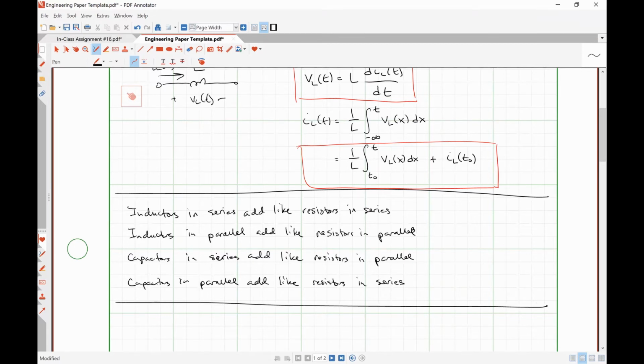Is that mostly because there's 2 equations and people probably get those 2 mixed up? No, it's more so because they don't look at the circuit during the transient condition, and that's very, very important. What I mean is that if you're not looking at the circuit at t greater than or equal to 0 plus, so if you look at the circuit at t equal to 0 minus and use that to compute your equivalent resistance, you're inherently wrong because the time constant depends on what the circuit looks like during the transient condition, not before that.